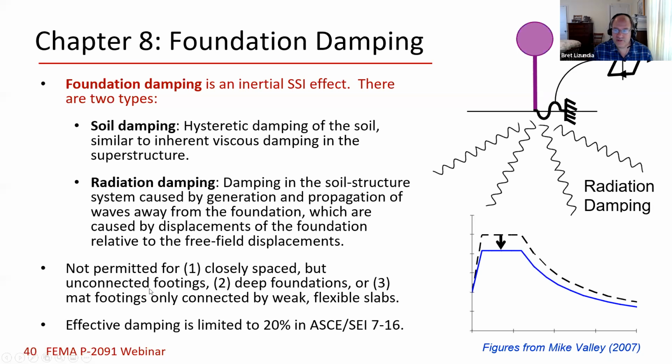Okay, chapter 8 is about foundation damping. So, damping, we traditionally have used a 5% damped spectrum to represent the damage and cracking of structural and non-structural elements in buildings. In the superstructure, the soil, we can add to that with this. This is kind of a freebie.